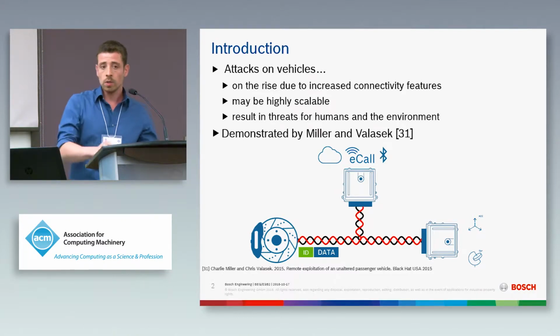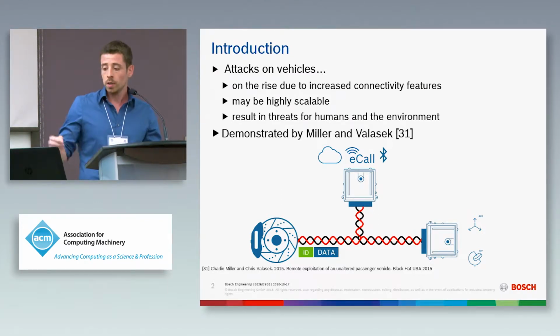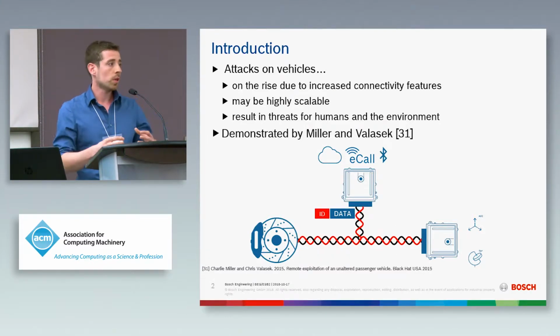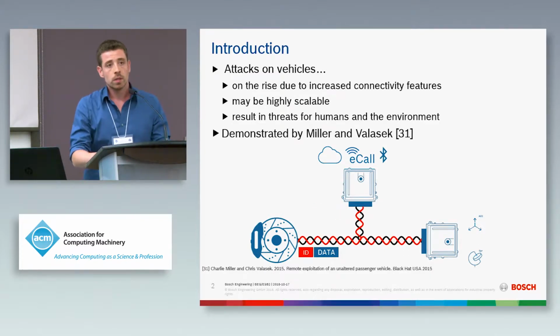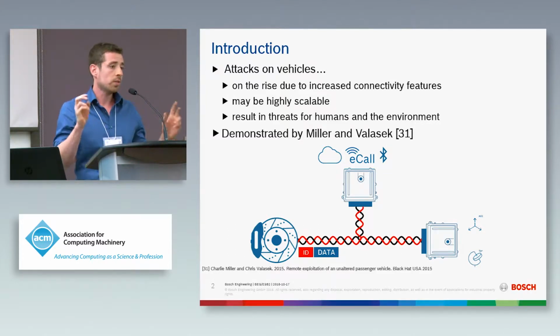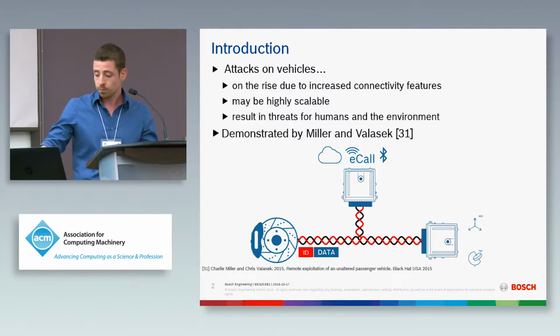And now we have a third ECU on the bus, which has, for example, some wireless interfaces, which can be attacked by an attacker. And now an attacker is able to use the same identifier, which is normally only used by one ECU. And the brake is not able to check if the now received message with identifier 10, for example, is really sent by the expected ECU.